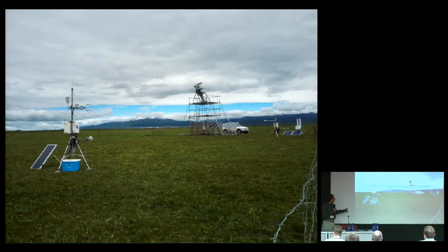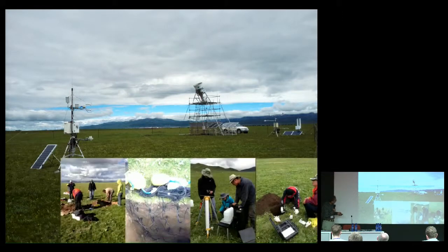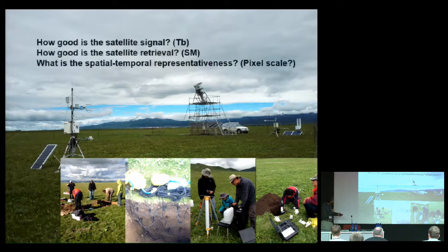So in principle, for this site, you can do modeling. You can check the algorithms. You can also look at the different types of retrieval results here. What we do in situ is basically we measure all the different soil properties, thermal and hydrological properties. We put up a very dense measurement network in terms of profile to see, from a radiative transfer point of view, to know exactly what is the effective temperature. And we calibrate a lot of the soil hydraulic and thermal properties also.